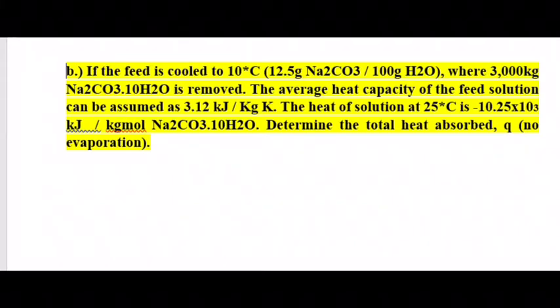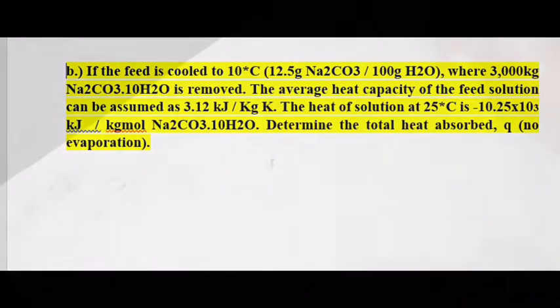If the feed is cooled to 10 degrees Celsius, where 3,000 kilograms of sodium carbonate decahydrate is removed, the average heat capacity of the feed solution can be assumed as 3.12 kilojoules per kilogram Kelvin. The heat of solution at 25 degrees Celsius is negative 10.25 times 10 to the power of 3 kilojoules per kilogram mole. So determine the total heat absorbed, with no evaporation.